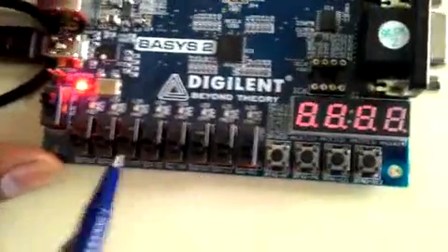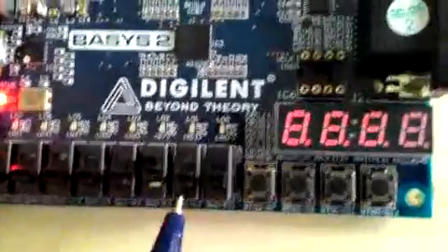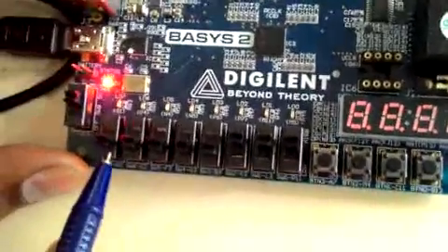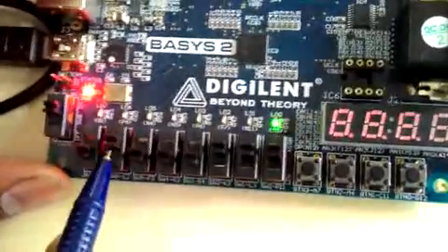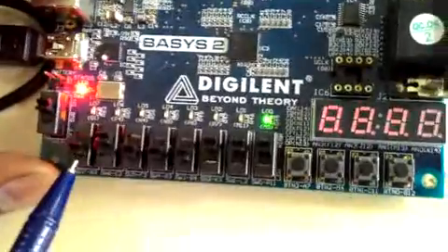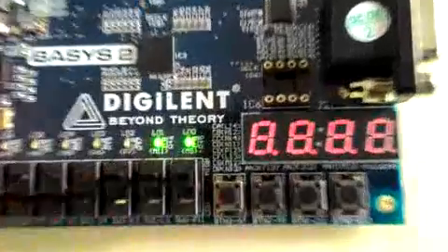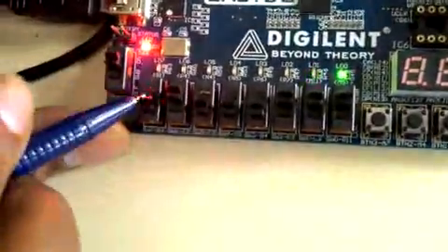If I want to pass the ALU, the ALU pass operation asks you to push the mode as 1 1 1, and by that time whatever I put on A will be passed to the output side. Now I have passed the ALU, so the A bit, which is 0 1, is passed. If it is 1 1, then 1 1 is passed. So that's it. Thank you.